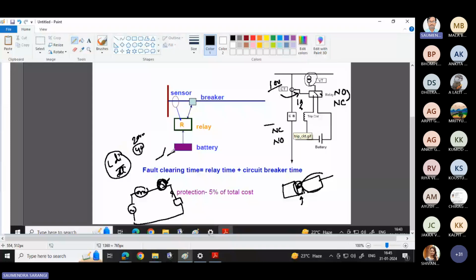So this switch, whenever you are trying to open it under high voltage, the air in between the contacts will be ionized. So sparking comes. When the sparking occurs, there is a chance that the switch, the circuit breaker, will burn. So whenever we are opening the circuit breaker, ionization occurs, and we need to evacuate all these ions which are responsible for the sparking or the flow of the current, right?